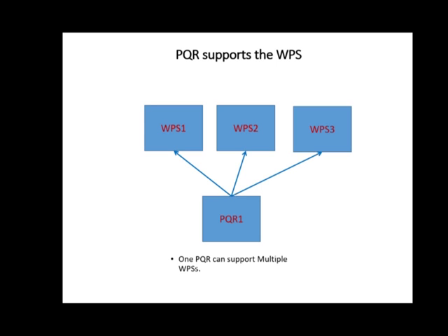And then let's say WPS number three, he wants a change on how it's cleaned. He only wants a certain kind of wire brush that's shipped in from Kazakhstan or something like that. Something that is not an essential variable, but it's written in there. So that WPS is different than WPS 2 and WPS 1. But all the essential variables are still supported by PQR number 1. When we did PQR number 1, we didn't have special wire brushes sent in from Kazakhstan that were blessed by the Pope. We only had what we got off the shelf. Well, the customer on WPS number 3, he wants his special stuff. So the PQR number 1 can still support WPS number 3, but WPS number 3 is different from WPS number 2 and also different from WPS number 1, but they're all three supported because they're using the same essential variables.